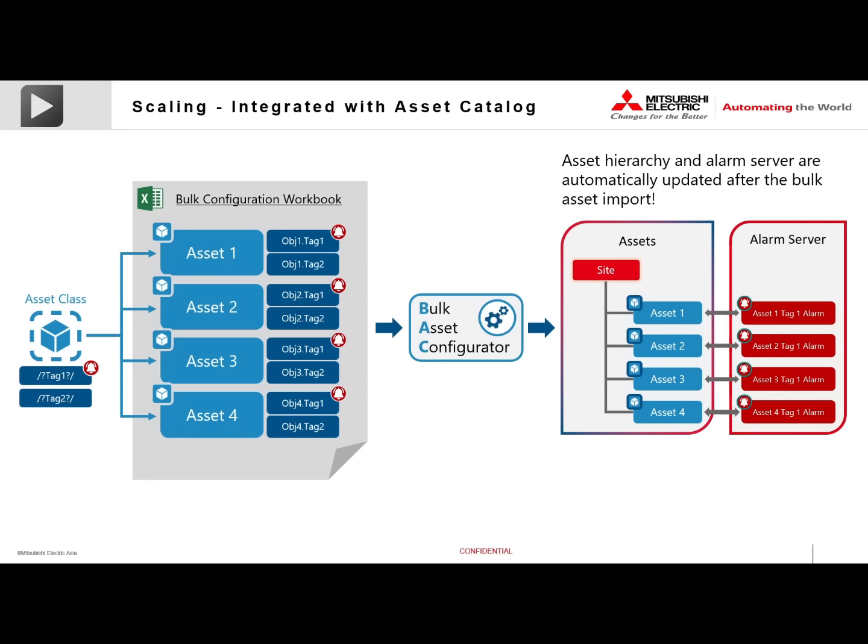You can create all your asset management, and once this asset tree and hierarchy is created, it will be used to automatically generate the graphic display using the concept of clone dynamics. So those words and terminology that I used so far, we hope that you can remember that we have these features and functions, and then you can acquire and learn about how this clone dynamics will work. That means if I configure one asset and keep on adding more assets, my display will keep on showing me as I go along. If I delete asset 3, it will automatically remove that asset from my graphic screen.